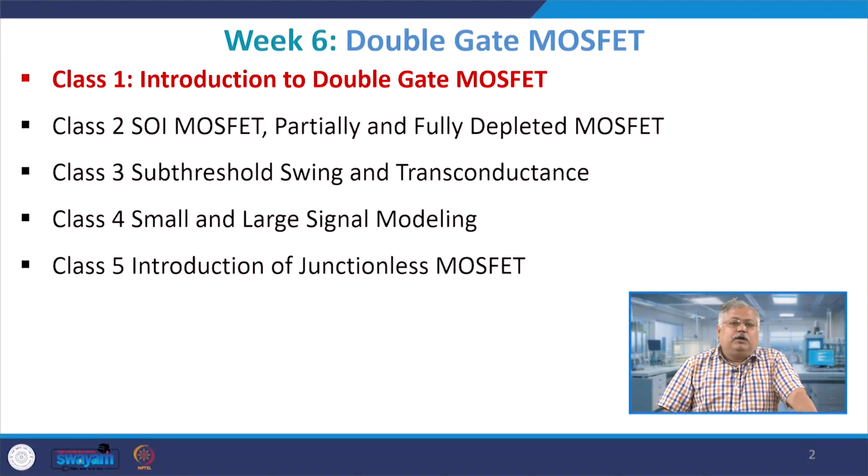Then we will look into SOI MOSFET, which is partially and fully depleted MOSFET. Then we will look into the subthreshold swing and transconductance, and then finally the small and large signal model, and then I will give you a brief insight about the junctionless MOSFET, a relatively new MOSFET which has come out replacing the conventional MOSFET.